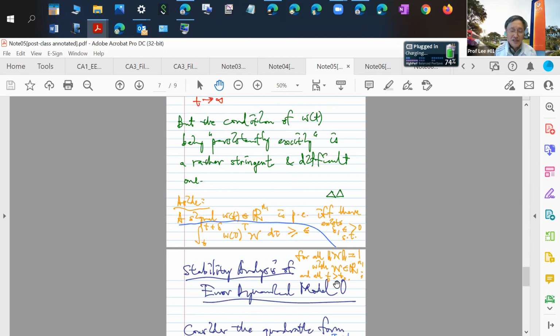So some people, you'll see in some journal papers, say, "Oh, my signals are persistently exciting because they're jumping all over the place." It's rubbish. Persistency of excitation is not that your signals are non-zero and jumping. No. It says that if you have n signals living in an n-dimension space, and you claim that your signals are persistently exciting, then you have to exactly obey this.